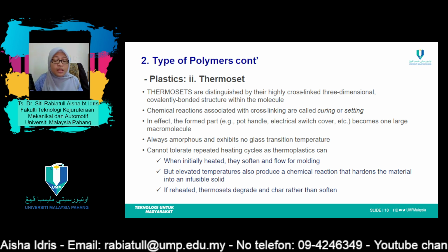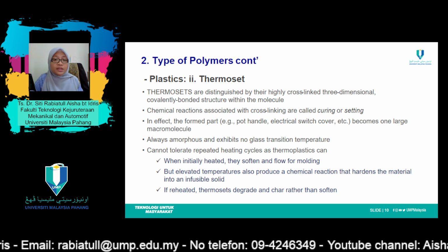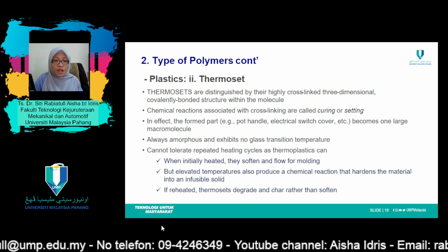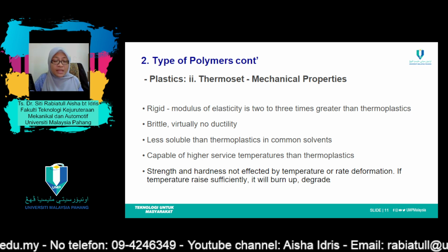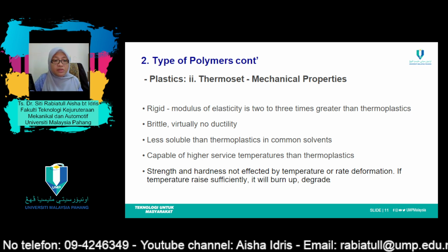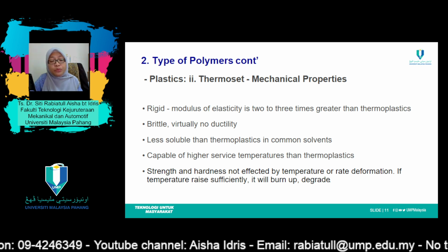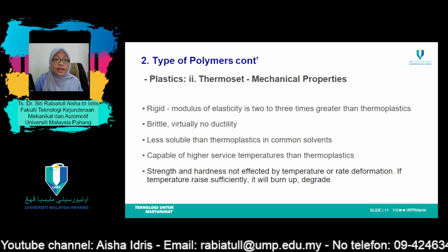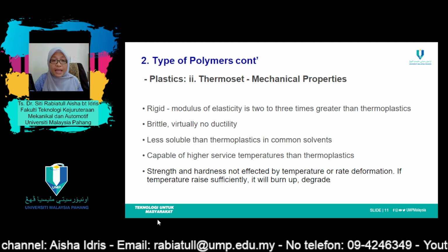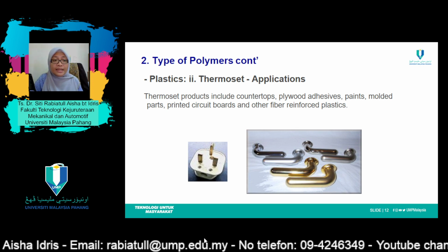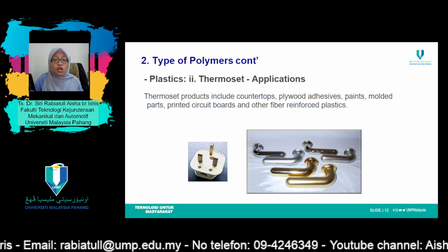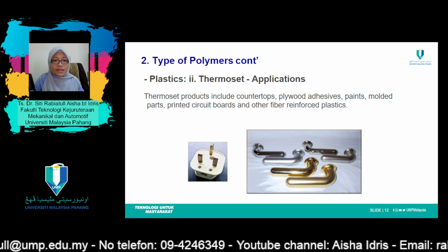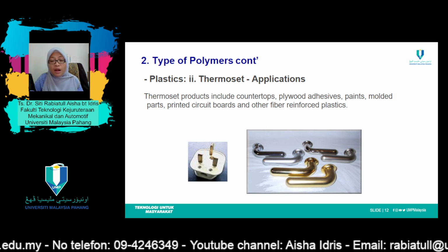Cross-linking is normally extensive in that 10 to 50% of the chain repeat units are cross-linked. Only heating to excessive temperatures will cause severance of these cross-link bonds and polymer degradation. Thermosets are generally harder and stronger than thermoplastics and have better dimensional stability. Most of the cross-linked and network polymers, which include vulcanized rubbers, epoxies, phenolics, and some polyester resins, are all thermosetting.